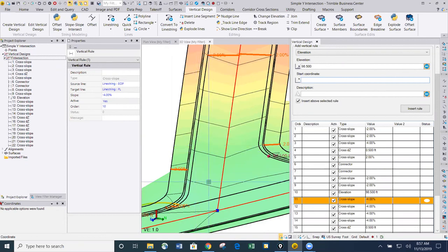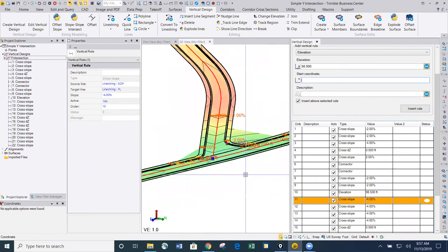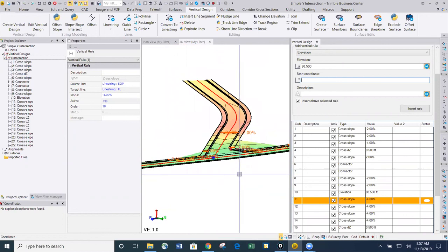Or if there's simple subgrade adjustments, you can just use the subgrade adjustment and drop those in on the surfaces here. So subgrade is something we know we need to work on and build out more tools for, and that will come over time now. But currently the tool is designed for single surface at a time, and you have to use the other tools to do your subgrades as it is right now.